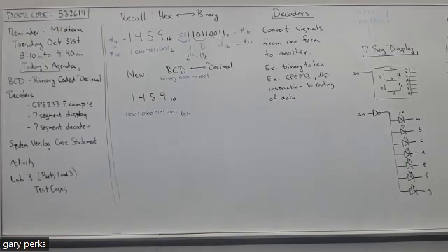Yeah, so you see, now what you'll learn when you take that class is that the ALU, which stands for Arithmetic Logic Unit, it ends up being modeled as a big MUX. Okay, so all those outputs of the decoder are going to MUXes, and specifically what input of the MUX? The select input. See, each of those 5 outputs is going to a select input of a MUX.